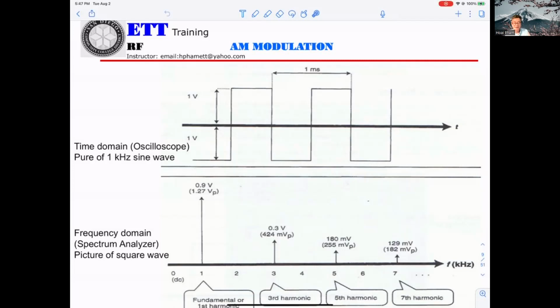The thing is, you can calculate when they say volt only. That's not a VRMS. That normally will be the average. So you would take the 1.27 and multiply it times the 0.636, which is the average.